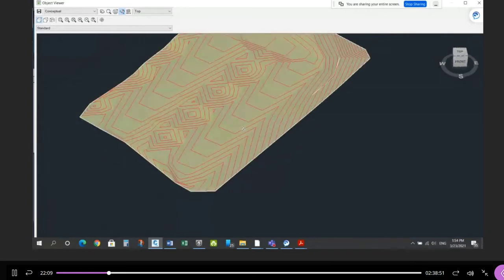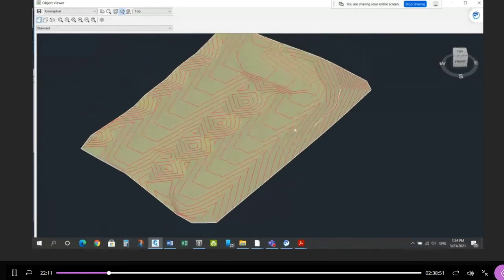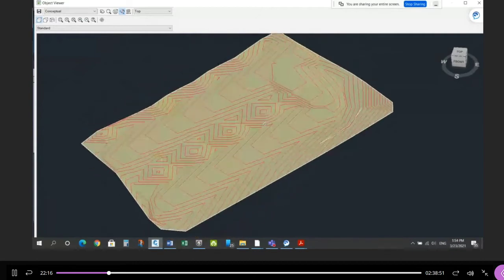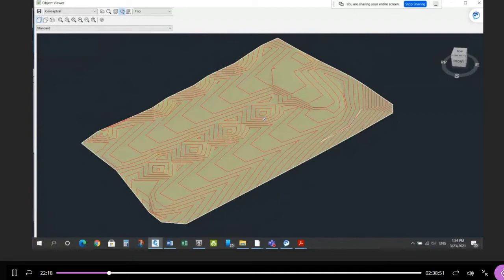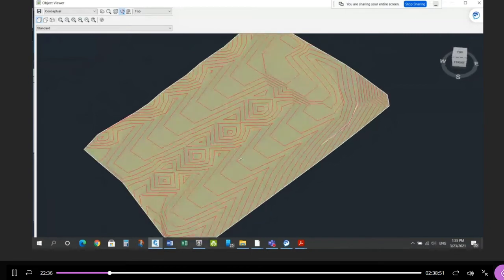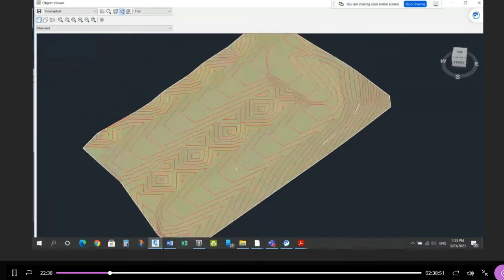It should have no spikes. It shouldn't have anything unusual on it. That's what your surface should look like. So if you look at yours in 3D and you don't see kind of what you see here, if there's anything kind of odd, out of the ordinary than what you see here, I started taking marks off, right? If the split point was missing, I looked. If this was missing, I took a mark off. If I didn't see these 1, 2, 3 low points for catch basins, I took some marks off. This was worth 1 mark all by itself. And then I made sure that there was the high point ridge and so on, and the pattern on the road. So this is what your surface should look like for the most part, okay?